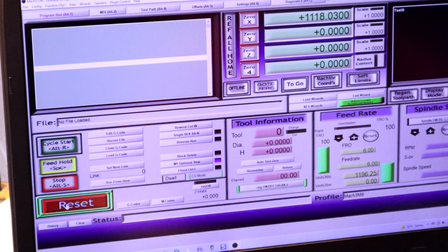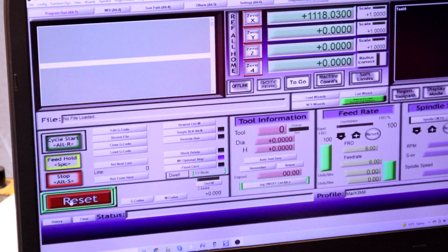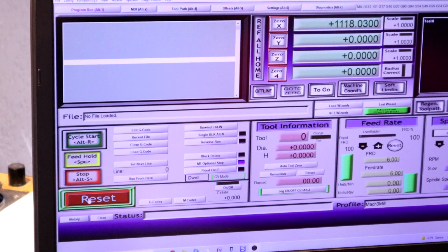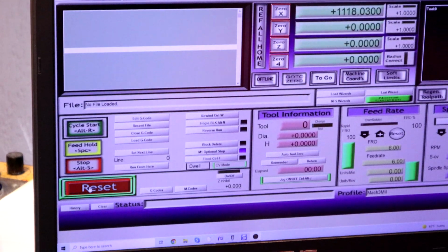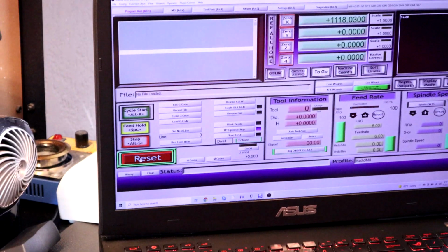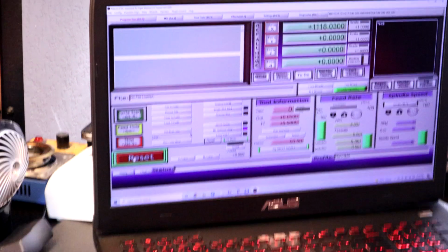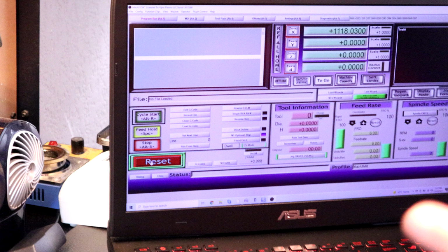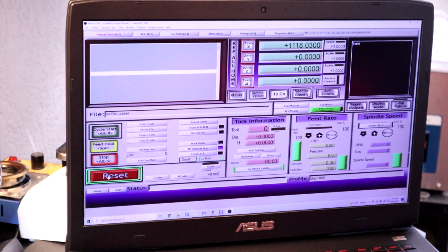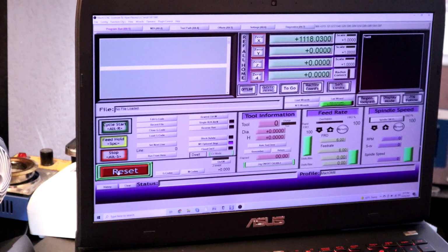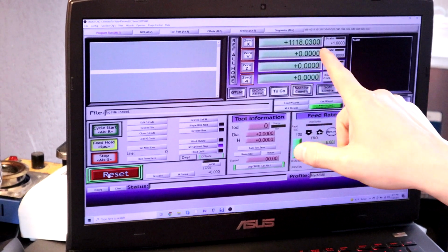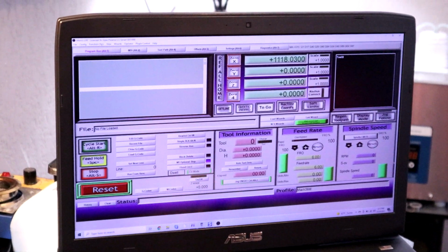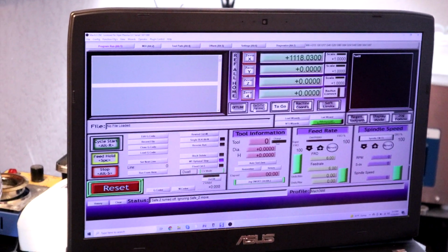Now we're at 1,000 inches. Why is that? Well, once again, if we think about it, if we're only saying 400 steps equal 1 inch, that's tiny as far as movement of the motor shaft to equate to 1 inch of measurement. However, if we decide to go like most systems and use ball screws, he's at 10,160 in his first video. That means his motor shaft has to spin much more in terms of revolution to equal the same distance. That's why you see this number greatly changed from where it was when we go to 10,160. You would see the same in terms of it going back. So I'm going to hit go to 0.